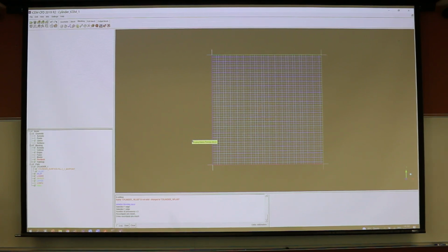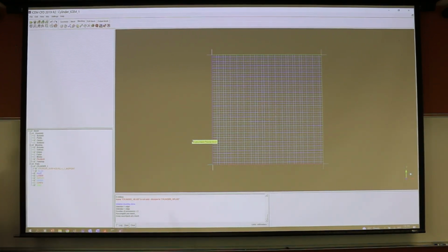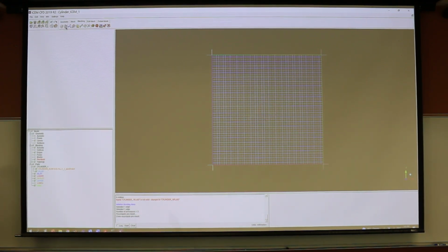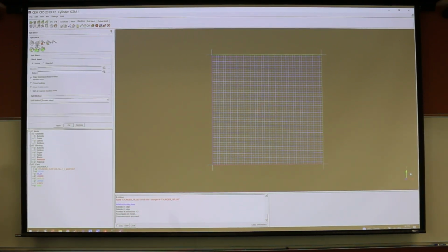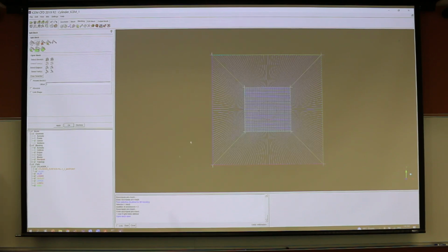So it takes time to grasp what the topology of your mesh is and how you can create it. One of the good tools in ANSYS that you can click here is the O grid. I will add a block inside my block, select that block, click the middle mouse button, and hit apply and regenerate.